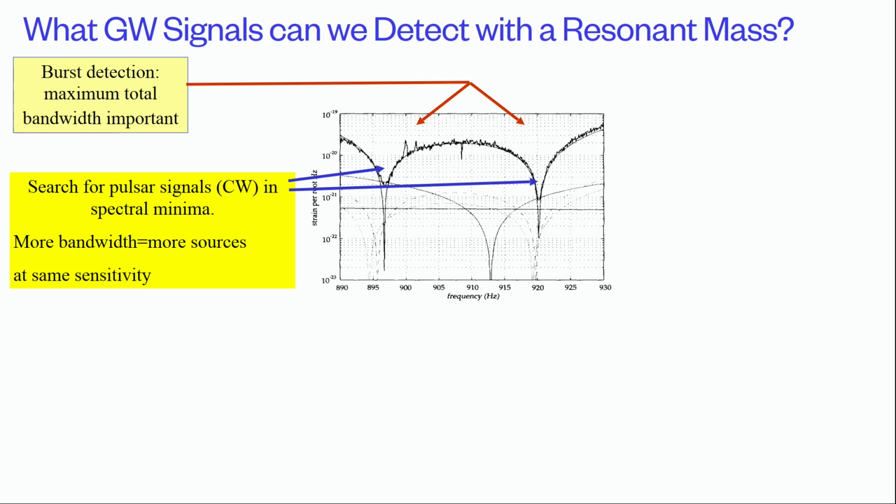So let me say that in another way. We know what the signal is. It might be a chirp, right? When you do an optimum filter, I left that out. I was going to put it in, but I left it out. You have to take the shape of your signal divided by the noise. Then the complex conjugate of that is your optimum filter, which will give you the best sensitivity.